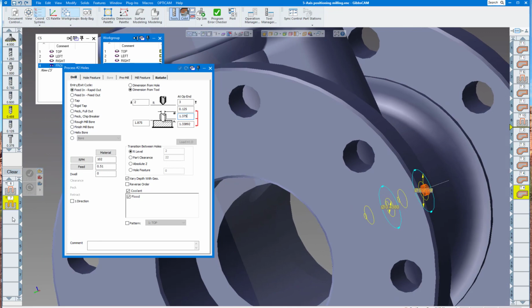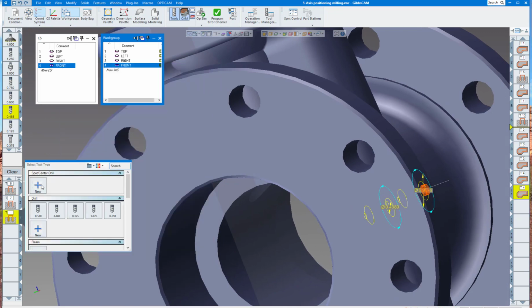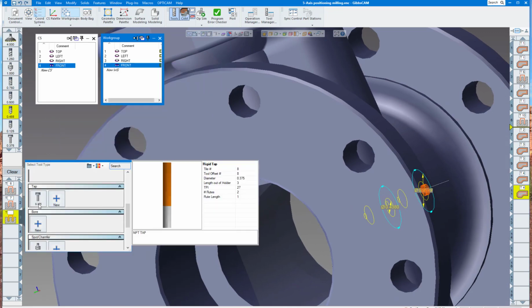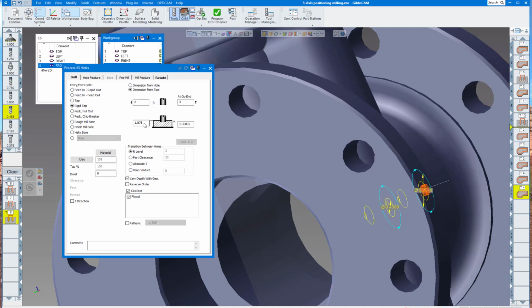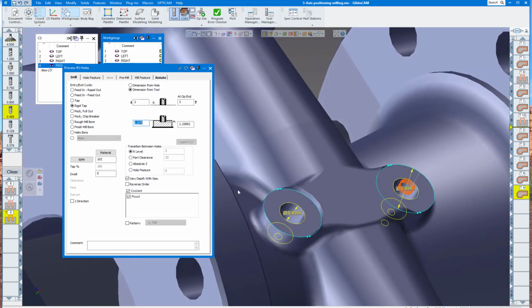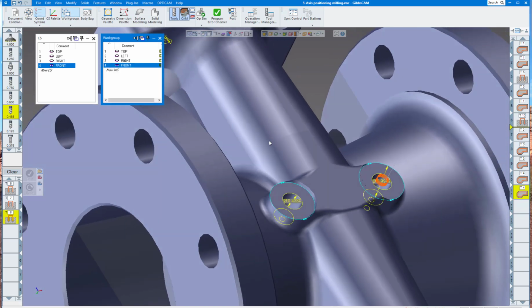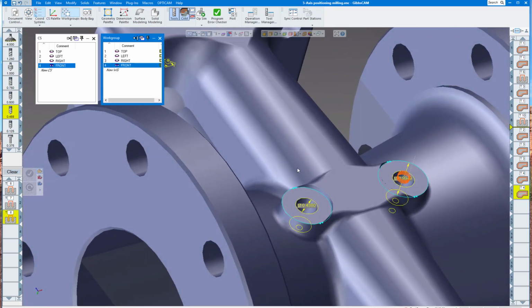And the last thing I want to do, another drill process with the tap. Again, I'll click the surface, 2.4, and I'm going to go down minus 1/2 inch with that tool. Rigid tap, adjust your RPM. Everything there looks pretty good. We'll transition up to 3 inches when we're done with this. And then we'll click on both the holes and do them at the same time.